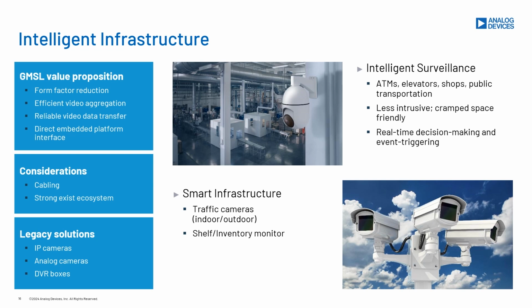In this application category, we sometimes face challenges to fit GMSL into existing ecosystem. For example, some infrastructures have pre-routed cables that are too lossy to support GMSL, which makes adding a GMSL camera less straightforward. But with the newer design, where we can plan from the beginning, this would be less of a concern.